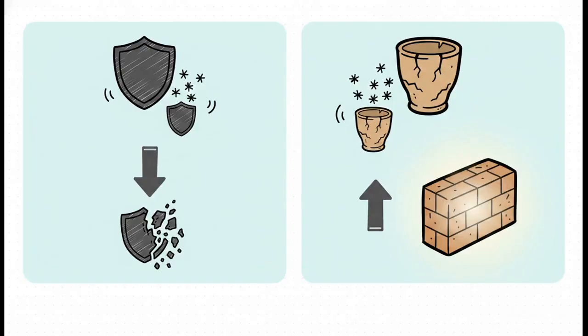Before we wrap up today's explainer, I really want to highlight exactly why engineers must constantly test things, and never, ever just assume. You might logically think that taking a plastic and adding strong, rigid glass fibers to it always makes it tougher. Actually, no, that's not true at all. Adding 30% glass fibers to polycarbonate, which is already a super tough plastic, drastically reduces its IZOD impact strength. It plummets from a highly tough 15 foot-pounds per inch down to a brittle 3.7.